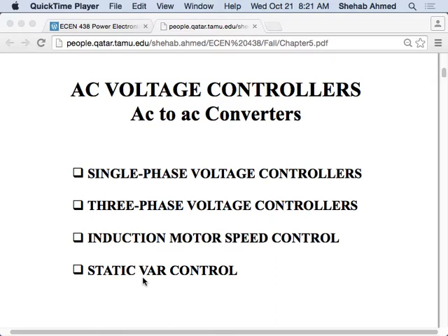So you can slowly apply a voltage to the capacitance and slowly remove it, meaning you can slowly add reactive power and slowly remove it. So it's a nice dynamic change of reactive power versus a sudden switch on, switch off application.